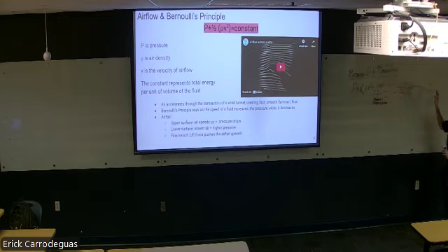The faster that air travels on the top, the less pressure there is here, it becomes negative pressure. This is known as the negative pressure differential, and that negative pressure differential and the speed here cause lift upwards. There's high pressure here on the bottom from the low speeds of the aircraft. That high pressure also causes lift, but not as much as the high speed airflow. Two thirds of the lift is generated from the top of the shape, and one third of the lift is generated from the bottom of the shape.